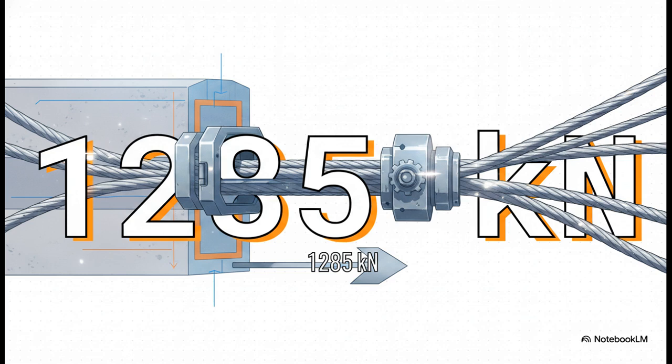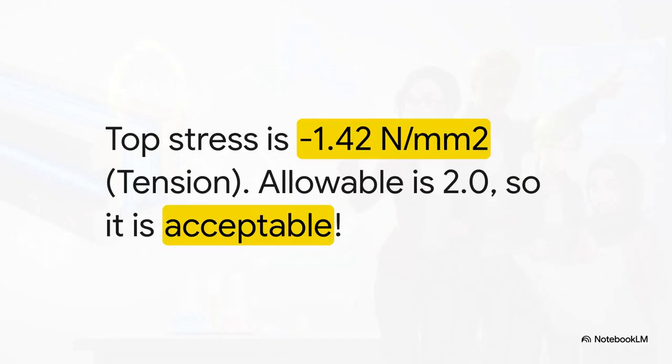Doing that math, we calculate a necessary pre-stressing force of approximately 1285 kilonewtons. To actually achieve that massive required force, we're going to need 10 strands of steel. But hold on. Before we look at the extreme failure state, we need to quickly verify what happens at transfer.